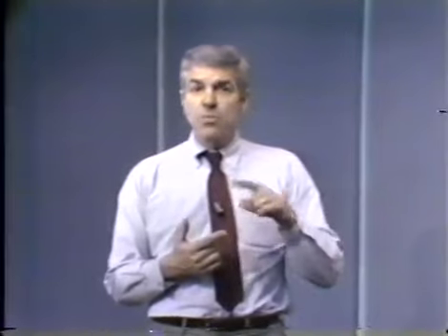Well, you can sort of argue the effects of that. In general, if we have a feedback system with very large loop transmission magnitude, the closed loop gain tends to go to the reciprocal of the feedback path. Here we have a lead network, a network that's high pass in nature in the feedback path, that tends to make the ideal closed loop gain be low pass in nature. And so as opposed to a system that had a frequency-independent feedback path, but the same lead transfer function somewhere in the loop, in particular in the forward path, we'd anticipate that applying the lead compensation in the feedback path would tend to slow up the response a little bit, tend to push down the peak overshoot, be a little bit low pass in nature.